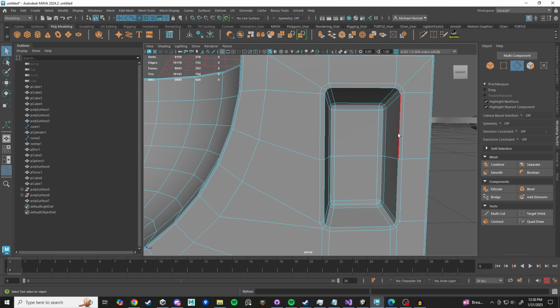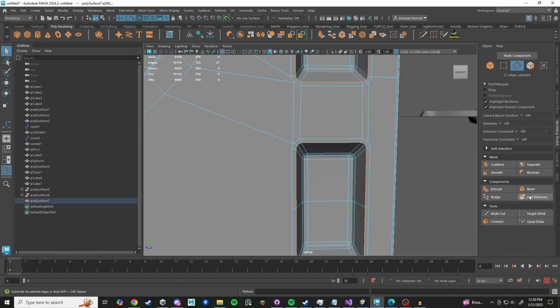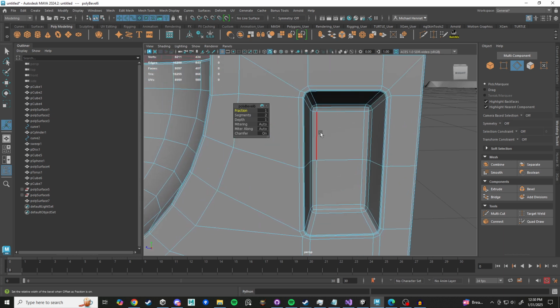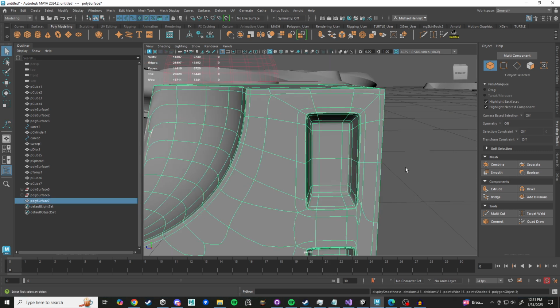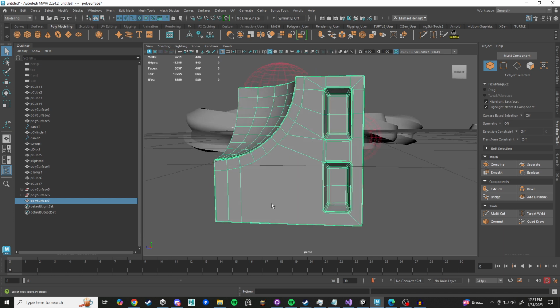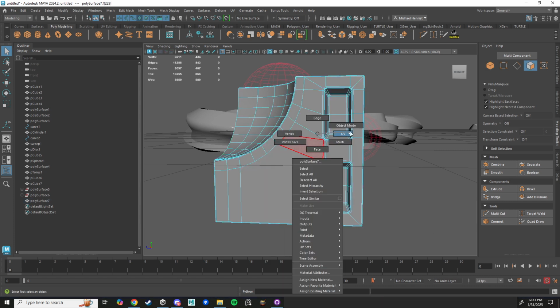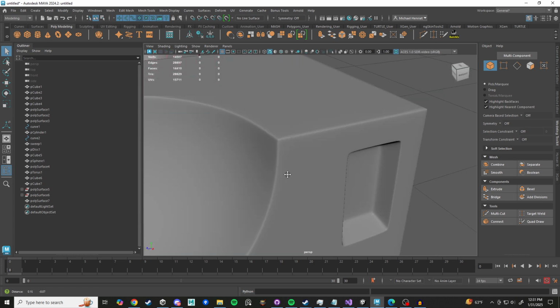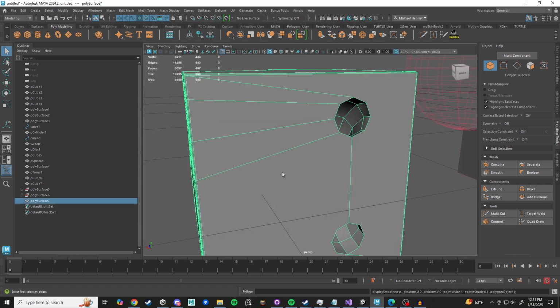We could also do ones around these guys, because you need some of these shapes to be maintained. There we go. That's looking good. And then let's press 3 on this to see. Look at that. So yeah, that n-gon right there, this fat one, is causing a lot of those shading issues down there. But look at the stuff that we've quadded out. It's looking very smooth, dude. So be careful with your n-gons and your Booleans. Those are really great tools, but they come at a cost.